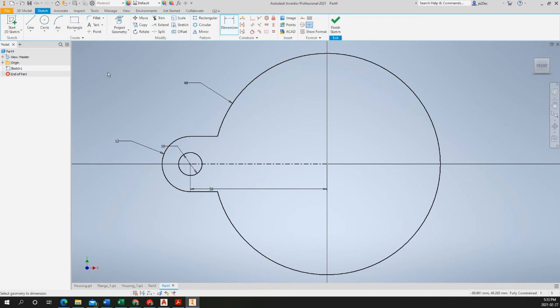So what we haven't seen yet in the sketching environment is how the fillet tool works. It's right here. I click that. A box comes up asking me for the radius for the fillet. And if I look back at my drawing, I can see that that should be 4. Now I will want to select the lines that'll get filleted. In this case, it's those.